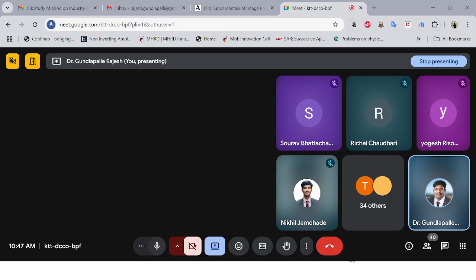SMLAL. Now what does this L refer to here? Actually, the instruction is MLA only. S refers to signed, the prefix refers to a signed or unsigned operation, and the suffix L refers to long. Long means your 32-bit number result will be converted to a 64-bit result. For example, a 16-bit result will be converted to a 32-bit result. So this L specifies long or short. Short refers to the size of the operand, and long refers to two times the operand.